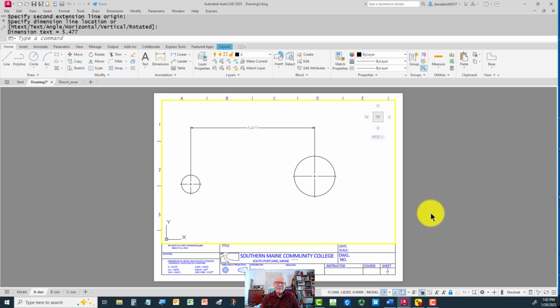Okay, this video is now about 45 minutes long, but just to make sure there's no question about it, let's talk a little bit about layers. Layering conventions can vary depending on the office. But one thing I would want you to do, and you have to do in this class, is to make sure that you have line type and line weight controlled by layer. So something else